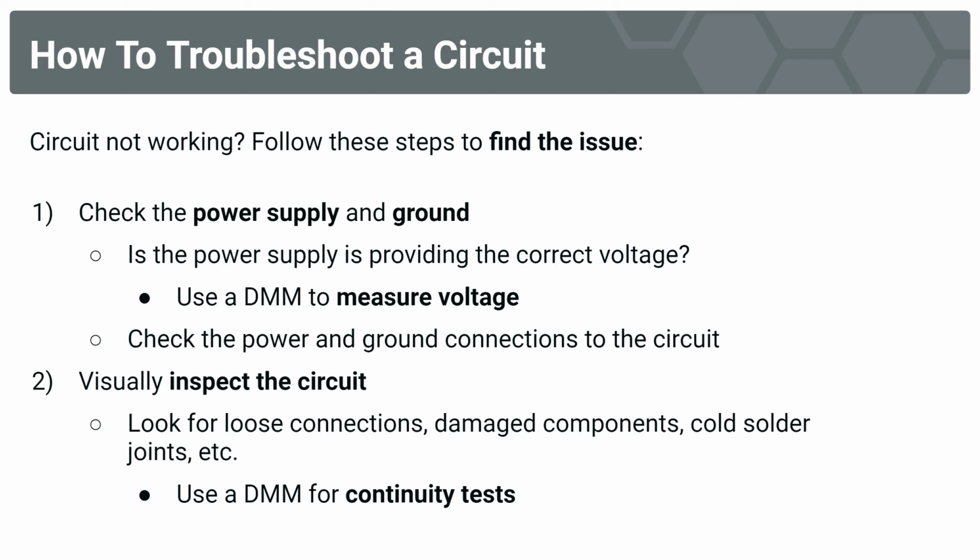In fact, if that quick scan is insufficient, or you found a connection that looks a little bit sketchy, you can use your digital multimeter for a continuity test. Test the continuity of that connection. If it beeps, you're good. If it doesn't beep, that connection is too loose. It needs to be redone.